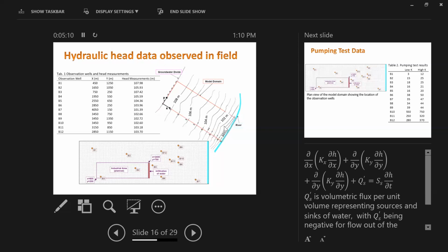So I think last time we stopped here. We defined this, we added the boundary conditions, recharge, river. I think we stopped at adding the pumping well. So let's add this pumping well, and then we also add the head observation. Let's do these 2 steps, and then we will see how to create a numerical model afterward, how to convert our conceptual model to a numerical model.